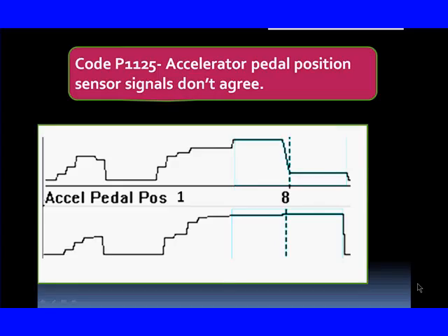Now, rationale. If these two signals have been agreeing all along, is it rational for APP1 to drop off when APP2 shows little or no movement? No, it is not rational. What happens is we had a slight increase in position for APP2, and that slight increase in position resulted in a drop in voltage for APP1. It's a dropout like we just saw in the world's worst sensor.